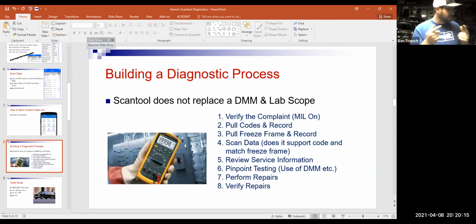So you actually have to know how to do those. And that's where your knowledge comes in about the multimeter class. Then when you figured out all that stuff, now you can do those repairs. And hopefully now you're doing pinpoint repairs. You're not doing what we call shotgun repairs, where you're just replacing all kinds of stuff. Oh, I think it needs fuel injectors, a computer, an oxygen sensor, and a coolant tank, right? That's a shotgun repair. You're just throwing everything but the kitchen sink on this thing. Try to pinpoint repair that thing and fix actually what's defective, and not just everything underneath the hood, and then verify your repairs. That's how you do proper diagnosis.